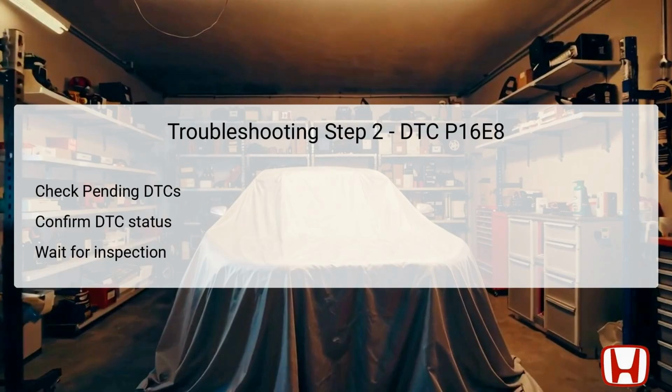In such cases, it's prudent to inspect the vehicle for any poor connections or loose terminals around the shutter grille and the PCM to ensure that all connections are secure. If the DTC was recorded in the onboard snapshot, it is advisable to attempt to reproduce the failure while observing similar conditions. Step 3 of the troubleshooting process involves another round of diagnostic checks via the Honda diagnostic system.